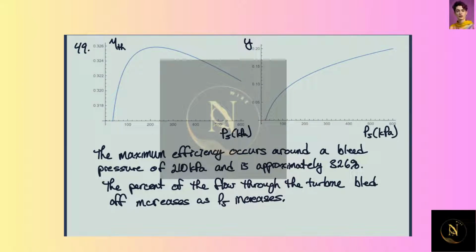That's the outlet pressure of the turbine. So again, Y is going to be zero there. That's a good check that your answer makes sense, that it goes to zero at 20 kilopascals, and then it continually rises. So at 210, right about here, we're bleeding off maybe about 12% of the flow. And as you go up in pressure, you're going to bleed off more and more to get the performance and other properties in the cycle.